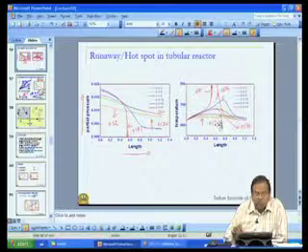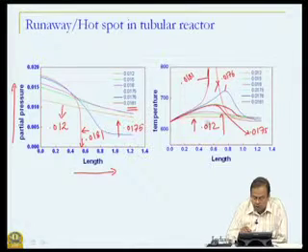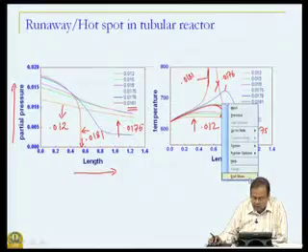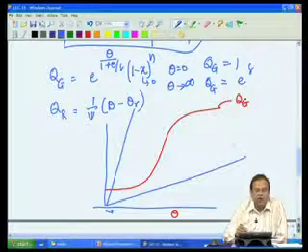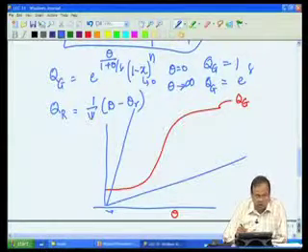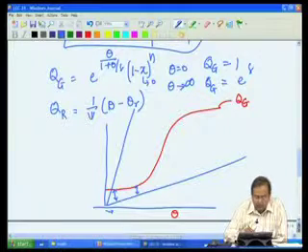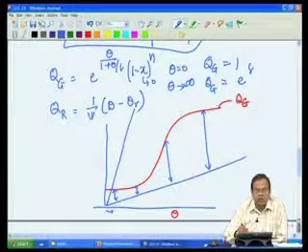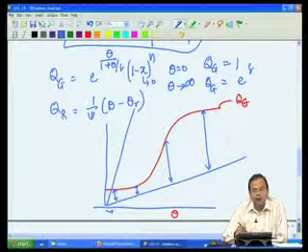This is what is seen in this particular behavior when partial pressures were low, that is temperatures are fairly rapid. But let us consider another situation where psi value is very high. So, this is the slope. Notice what is happening as temperature is increasing. The driving force, it appears that it will go down, but then it goes on increasing, or in other words, generation term is in far excess of heat removal term, and that is where we will get our hot spot.